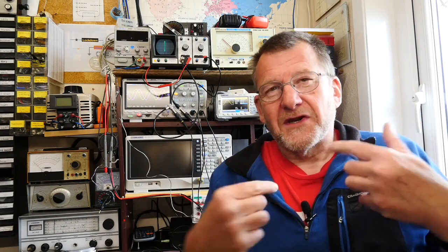But generally most hi-fi buffs will tell you that if the speakers are out of phase, it usually manifests itself in a sort of thinner sounding bass response, which makes sense to me from a scientific point of view, because obviously the lower frequencies are the longer wavelengths, and the human ear is more likely to detect those changes in sound pressure. As the frequencies increase, those wavelengths are a lot shorter, and I guess our ears probably can't keep up quite so well. So let's now have a look at the effect of phase on a particular type of discrete component, the transformer.